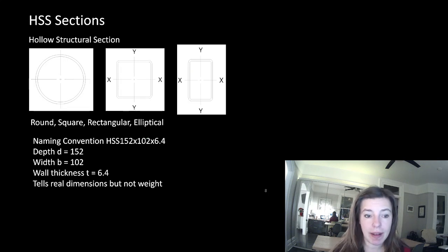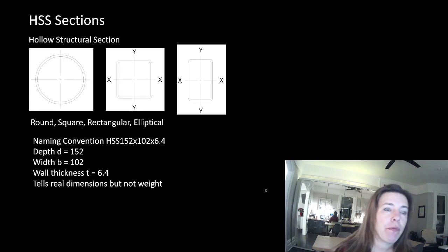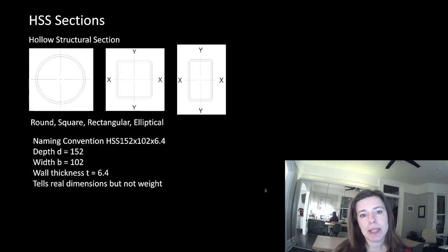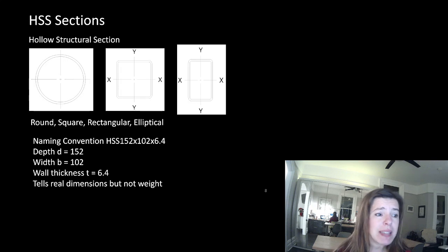That's something that, every 4 years, say, somebody shows up in town representing a company that makes elliptical HSS shapes. They give a presentation. The next project, architects always want elliptical HSSs. So the next architect that says they want it, I'll spec it on the project. And sometime in there, that particular company either goes bankrupt or we find out there's like a 10-month lead time to get them because they're only made in Europe. And essentially, I've never actually gotten them put on a project.